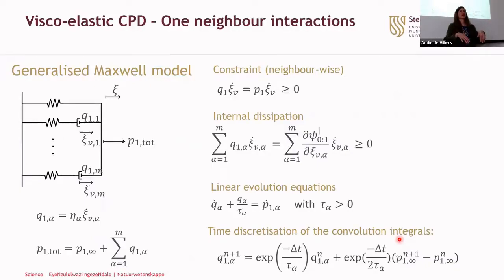Do you mean how to get them or how to compute them? Oh, with this. So we do time discretization based on Simpson's rule, and you get this. This is what you put in your code. It's a recurrence formula. So it's really based on the value of your energetic force, but I choose this as 0. Every step you compute one and then update it. Yes, so it's a history variable. If this was 0, you just have elasticity again. So for each time step, you just update this energetic driving force.